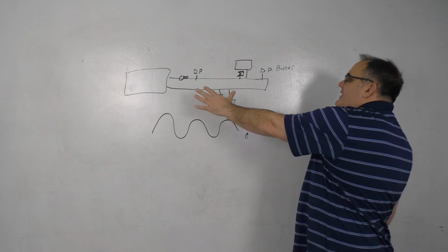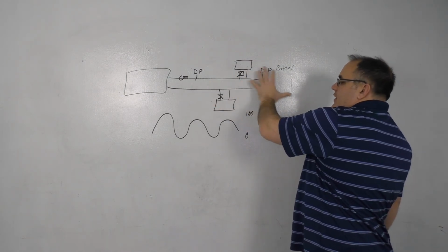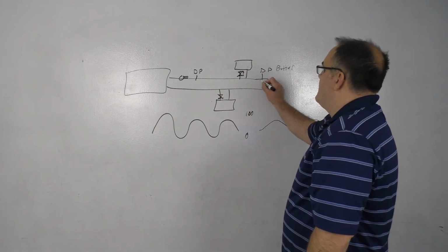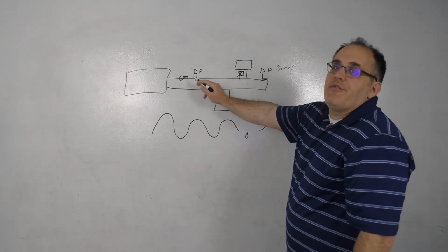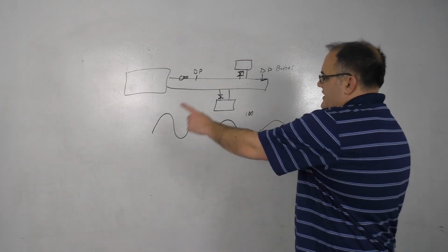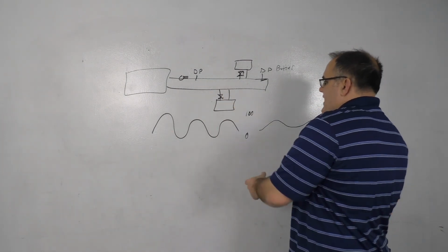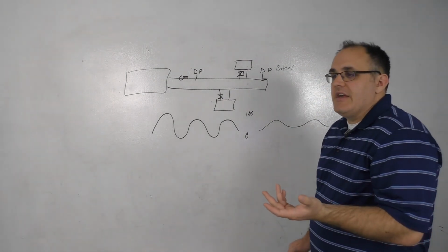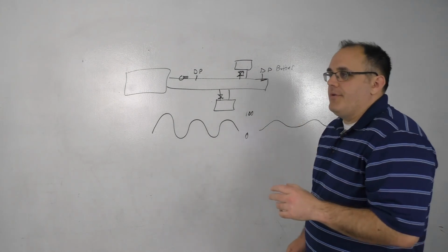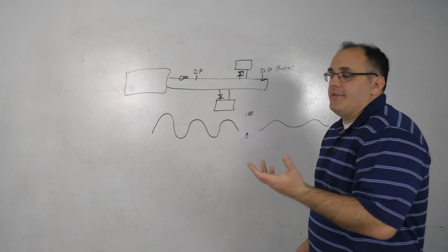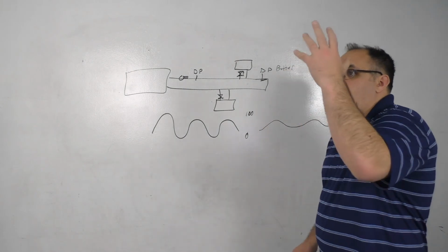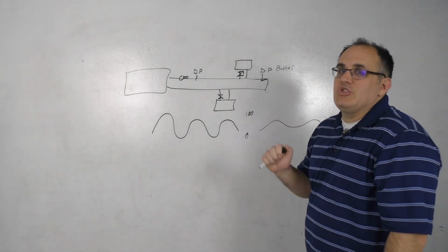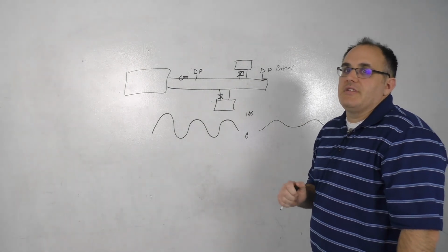But you're giving the pump time to actually fill the loop with water at the right pressure, and thus meet differential pressure, versus meeting differential pressure immediately and causing the pump to cycle up, down, up, down. So this is kind of a tip. If you run into plants or air handlers where the pump or the fan are ramping up and down, then it's most likely that your differential pressure sensor is too close to those devices.